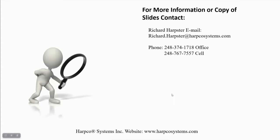The question is what ends up in the cause column, and what ends up in the requirements column. In the cause column of your design FMEA created in the AIAG 4th edition format, if you create that FMEA using the structure, function, and failure nets, you're going to stick failure modes in that cause column, and that line of the design FMEA is going to be useless.